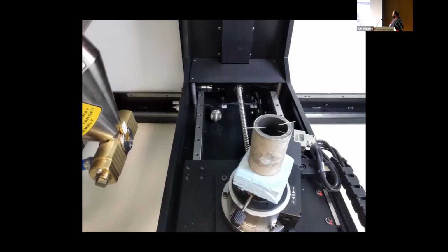So this is an example of additively manufactured parts. Again, for the outer part, obviously, we could have used a profilometer or another traditional instrument or method. But if we want to access the internal surface roughness, we don't have the tools here. So this is why we use X-ray CT here.